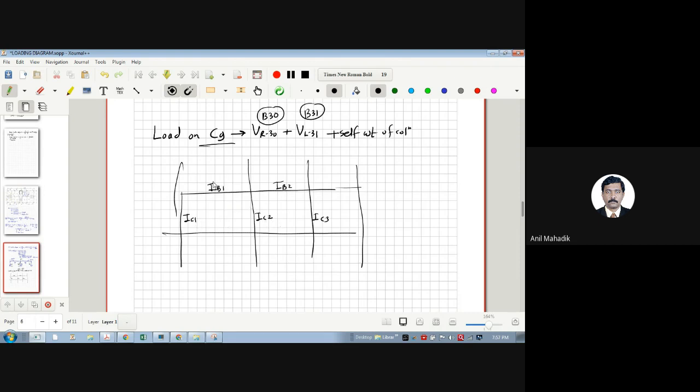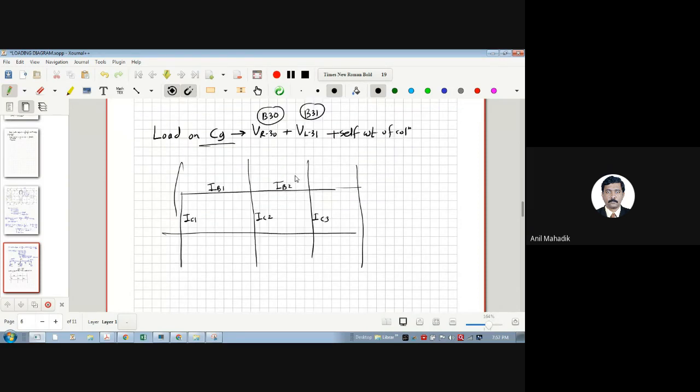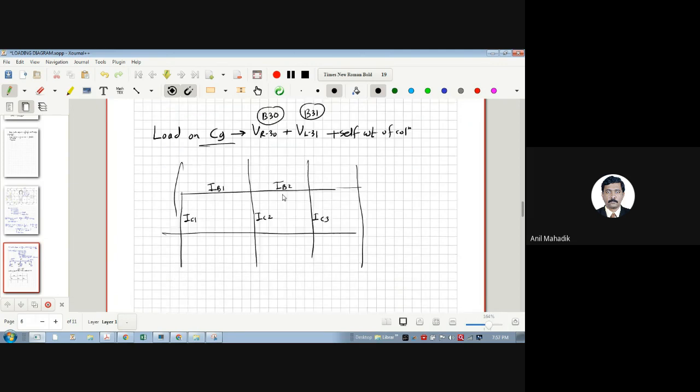As there is a difference in moment of inertia, moment distribution is generally not as easy as we draw here, as we do it manually. Whatever we learned in the manual concepts is not always the case. The real case is complex, and it requires the moment distribution method and stiffness matrix method. So even this 0.4 and 0.6 is not valid. Finally, we refer to the software results because they take care of all these moments of inertia.